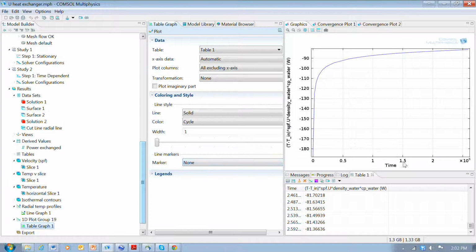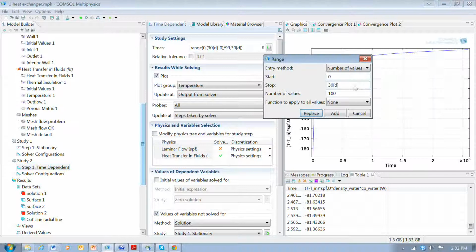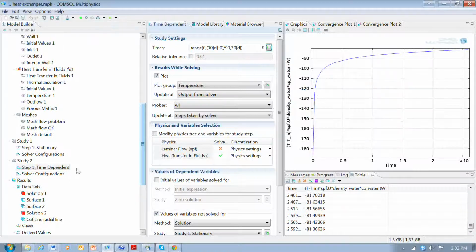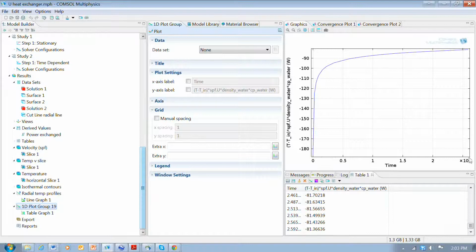Well, at any rate, I think the total elapsed simulation time is 30 days. Okay, so I specified it. This is a little bit easier way of specifying the duration of the simulation. You can give units here, and so this is 30 days, but you notice that it's taking that specification for the runtime of 30 days, and it converts it into the internal units of seconds that it uses to do the calculations. And so then the display here is in units of seconds.